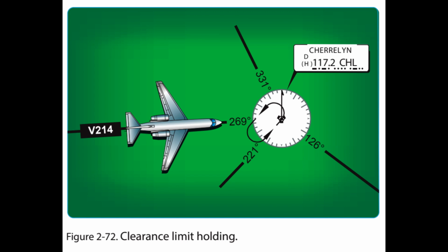Where required for aircraft separation, ATC may request that the pilot hold at any designated reporting point in a standard holding pattern at the MEA or the MRA, whichever altitude is the higher, at locations where a minimum holding altitude has not been established.